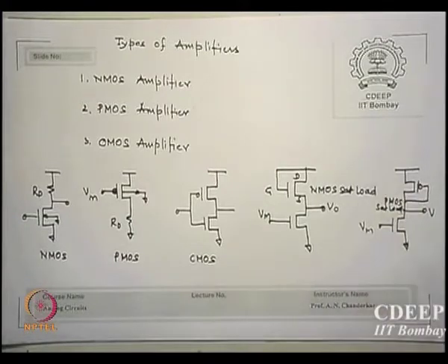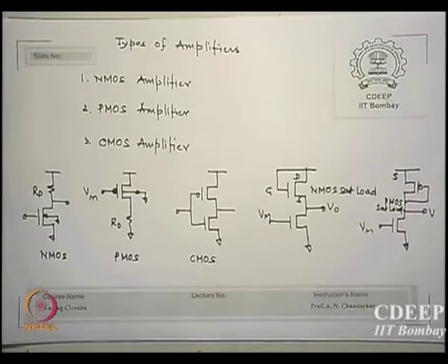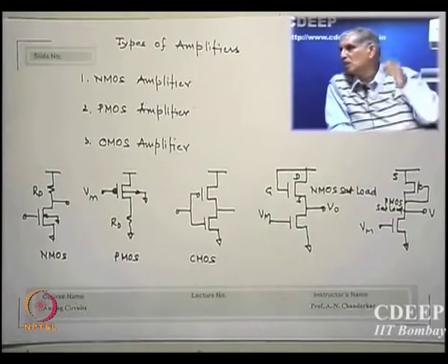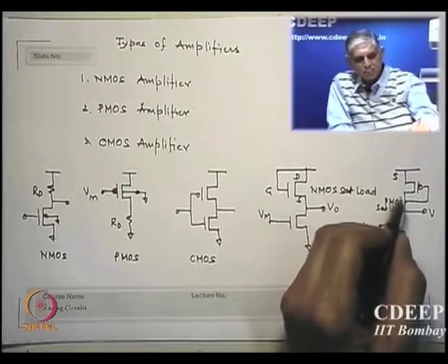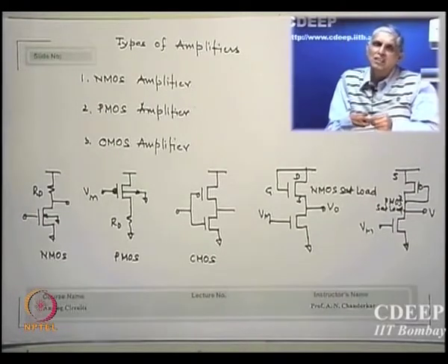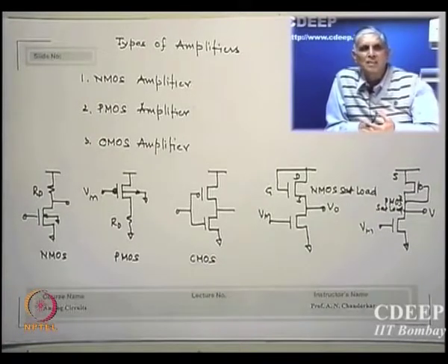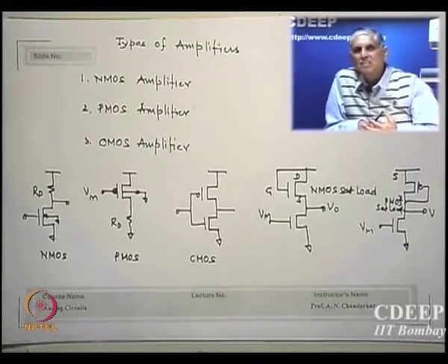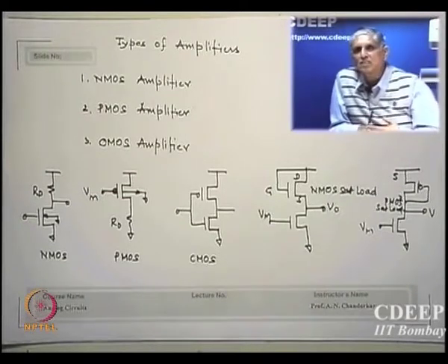By the same logic, can you think which will be the source here? The upper one, because now holes travel in the same direction as the normal current, positive polarity down. So this is source, this is drain, and again the gate is connected to drain. Whenever gate is connected to drain, whether in N channel or P channel, the transistor will enter saturation, and its equivalent resistance can be evaluated by finding the W by L. We will write the equation, and we know what resistance we are offering.